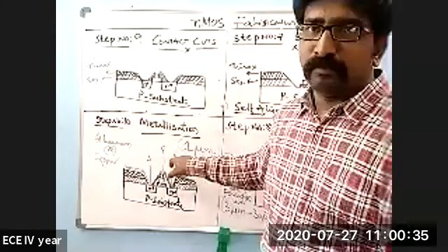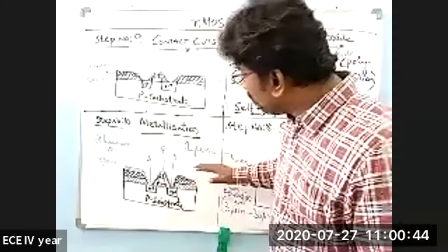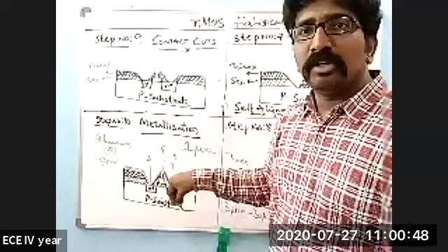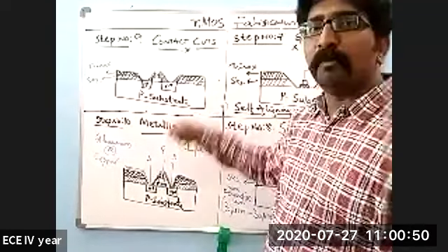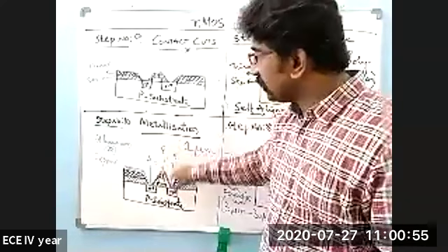Here, first is metallization only. I have drawn it here only to show you that. After that, again after the etching process, these 3 layers will be pulled up. Have you understood or not? Okay. Completely metal will be laid upon this integrated circuit. Metal will be laid upon this entire device. Then after that, the etching process will be done. After that etching process, the interconnections will be pulled up. These are the 3 interconnections. In order to make you understand, I have drawn blue lines.